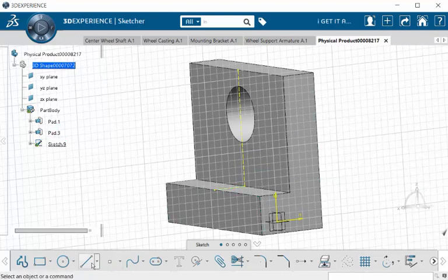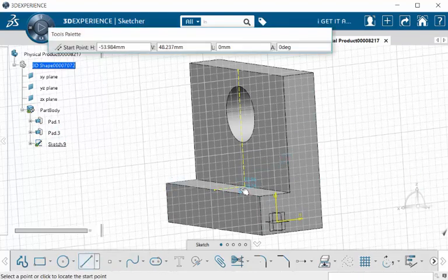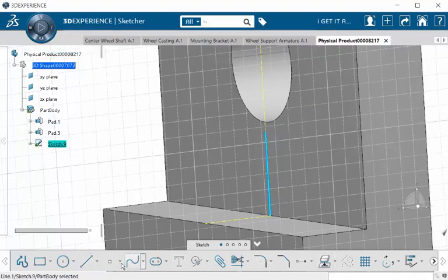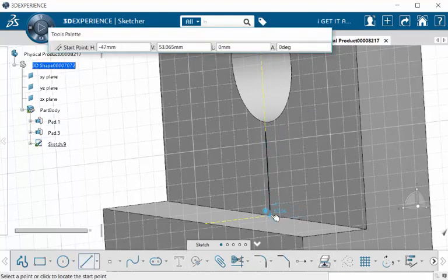And next, I'm going to use them, and notice I'm going to get those points so they're perfect onto our model. And actually you can use that to place them on that construction element. And then also I'm going to do the same thing this way. Notice my little concentric circle, the dot is filled. That means I'm on the point of that element or line.